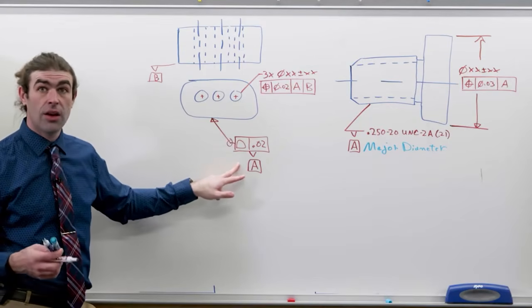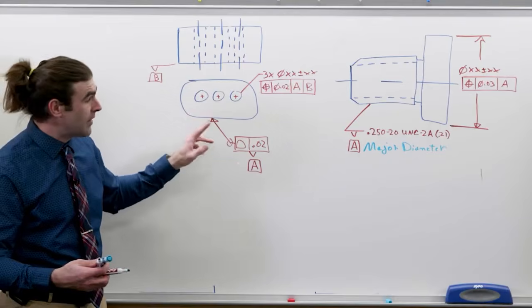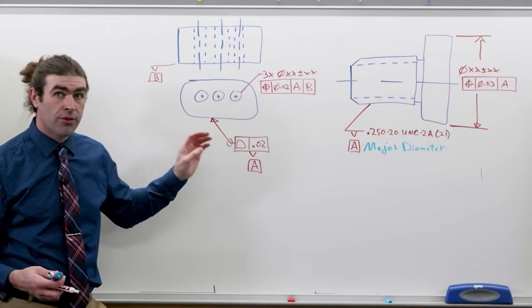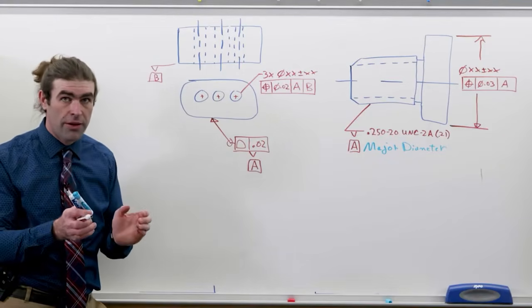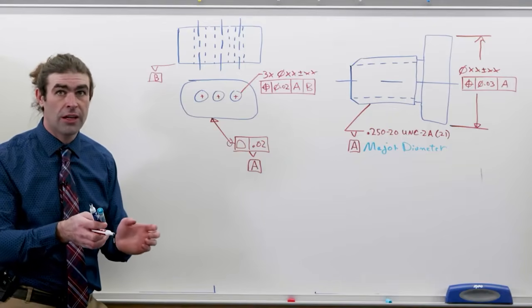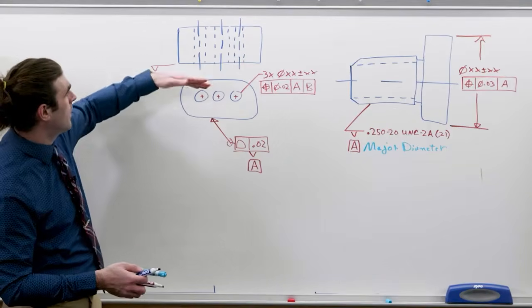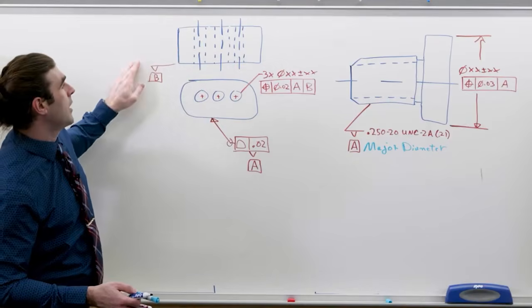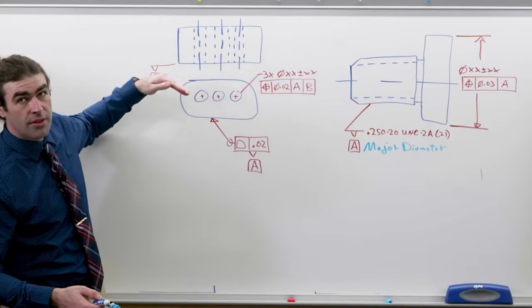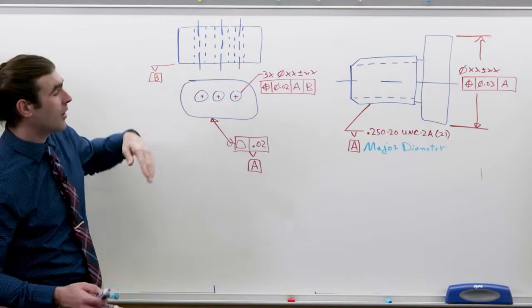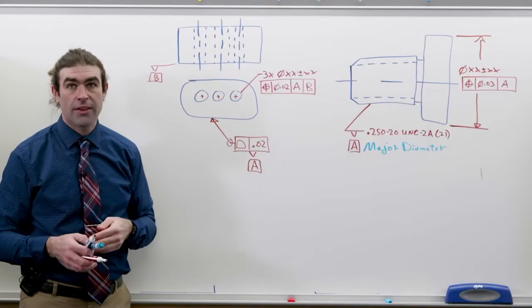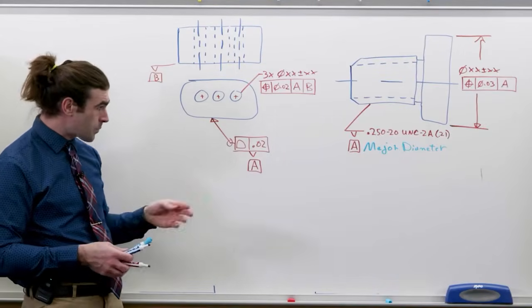This is allowed. So that takes away 5 degrees of freedom, right? Because it's a special shape. It can't move in any direction except up and down. So datum B is one of the top or the bottom of this part that locks down the last degree of translation.